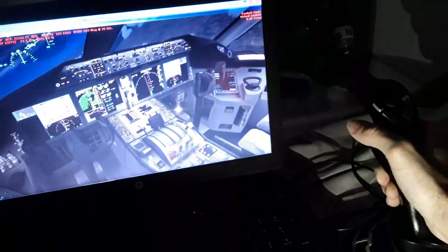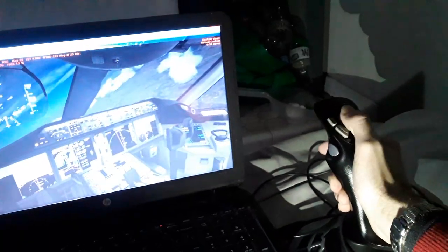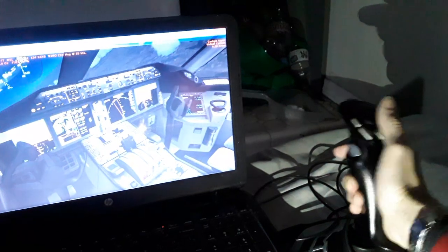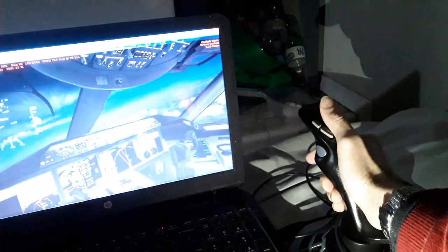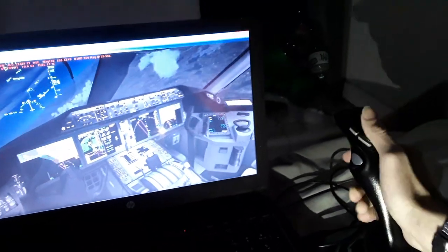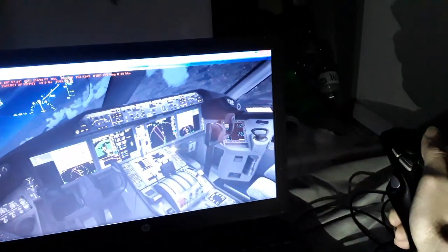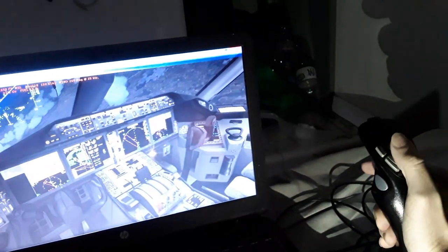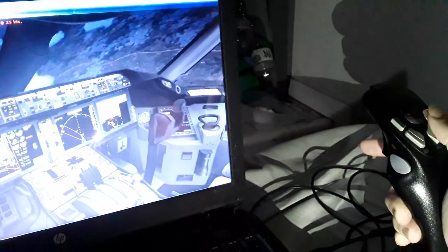So we make the turn here, as you can see. You can level off, you can move the aircraft like this. You will level off quite fast, quite easy. You can see how fast it turns. You can use a little bit of right rudder for the turn. And we have 10 more minutes left for this flight.